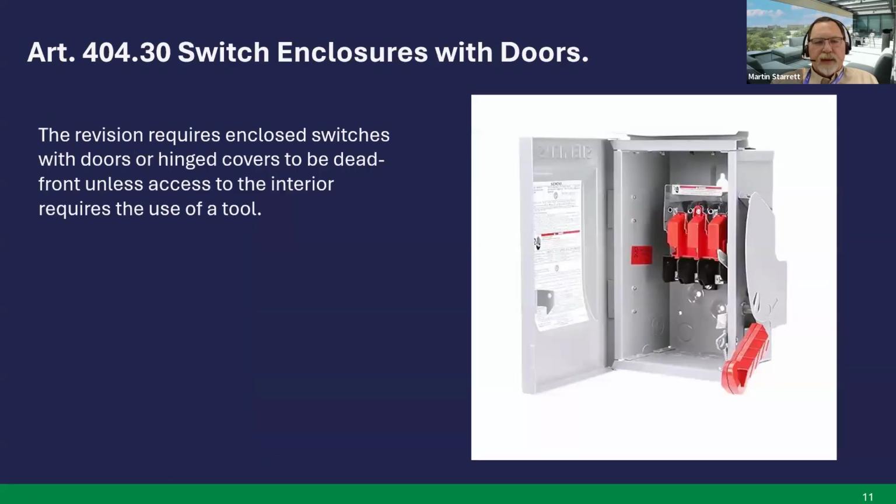Next slide. Article 404.30, switch enclosures with doors. The revision requires enclosed switches with doors or hinged covers to be dead front unless access to the interior requires the use of a tool. Most of your heavy duty switches, you're already required to use a tool to open them, but there might be some general duty that you might have to watch for with this particular revision.